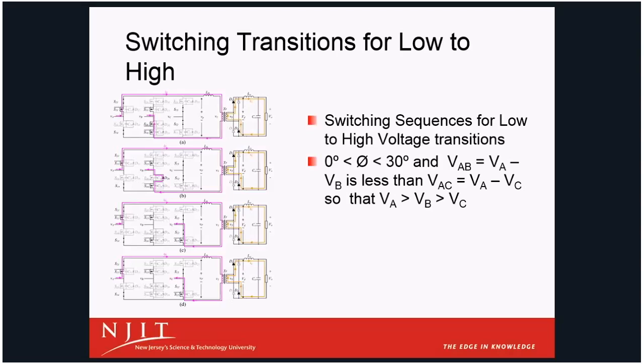Switches 21, 14, and 15 and 22 are always kept on. And the reason for that is so that you can have synchronous rectification and it minimizes your switching needs as well. Also 13 and 26 function as synchronous rectification.